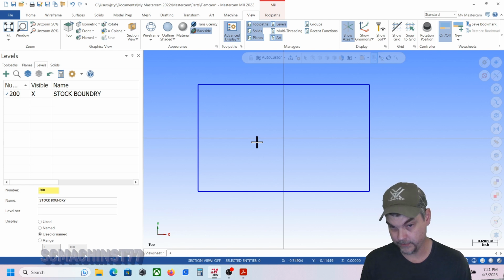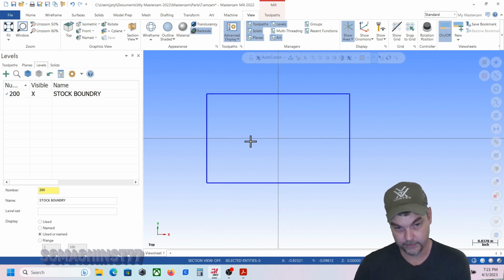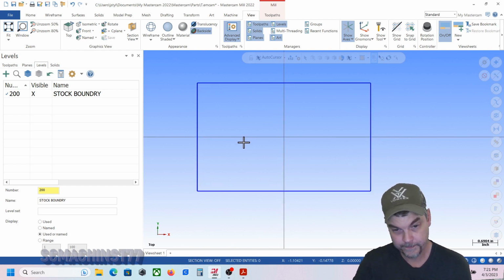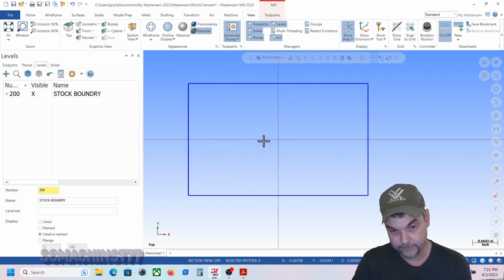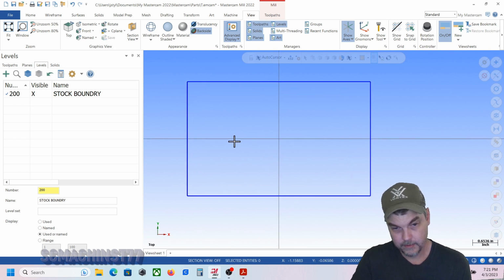Do it the hard way so that you know all the ins and outs of everything, and then when you start using solids, you've got a better idea of what you need, because you can do solid chains and things like that off of the solid model, but you're still going to need certain wireframe geometry for certain toolpaths later on.